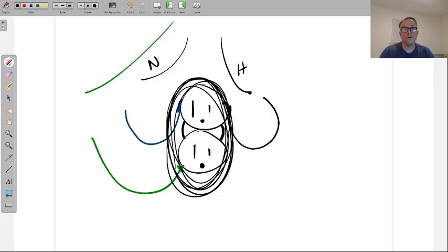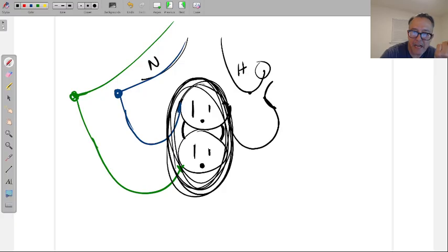And now we go in the order that we always land everything. First the grounds, safety first, ground is bonded. Then the neutrals, this neutral and that neutral, there should be nothing there. You're safe so far. And now you only have to worry about one hot splice. And technically you only have to worry about one wire. It's just that one that's hot.